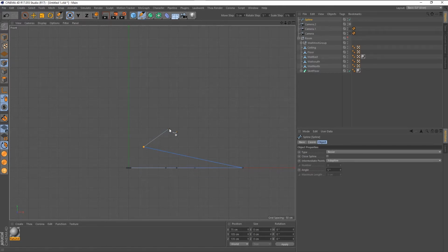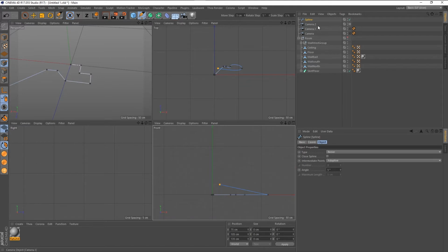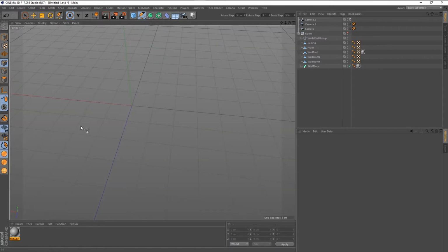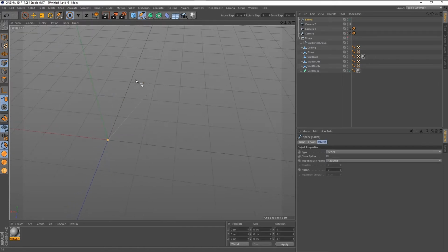Anyways, typically, by the way, if you're going to draw a profile for a skirt board around a floor, what you want to do is, I'm going to delete this here. So you just select it in the thing and hit delete button. What you want to do is draw your plan view using the pen tool. You want to draw your rail. Come on, be close. Okay. Your middle mouse button, click inside that view and it switches back and forth.